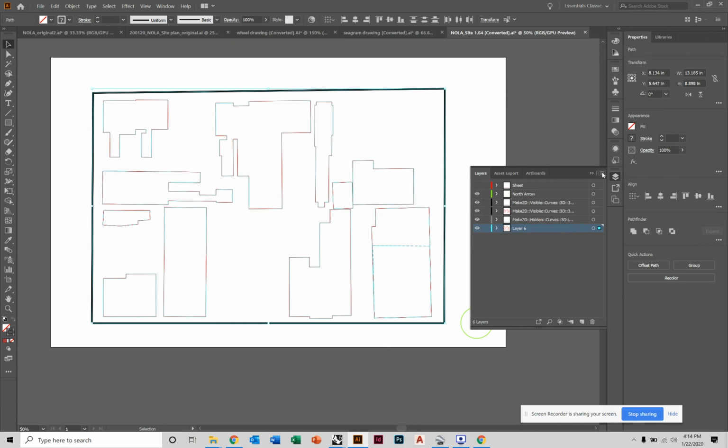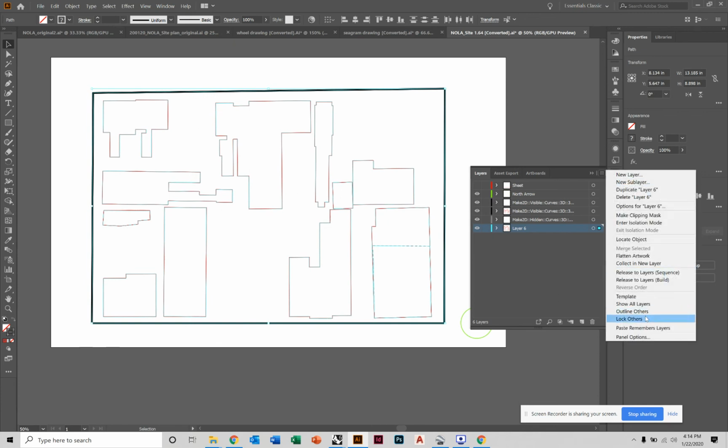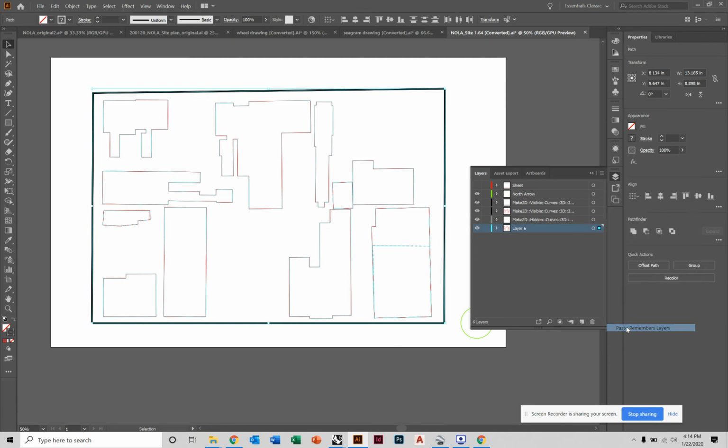By the way, if you want to copy something, and let's say you want to paste it on another drawing and maintain all the layers, there is an option called Paste Remembers Layers. So you don't have to one by one individually move things. Saves a lot of time. If I have this on and I do what I just did, I select everything and copy it, I think it's going to drop here, it won't. It'll paste it back on the original layer because I have Paste Remembers on. So if you're running into that, that's why I'm showing you, just turn it off.